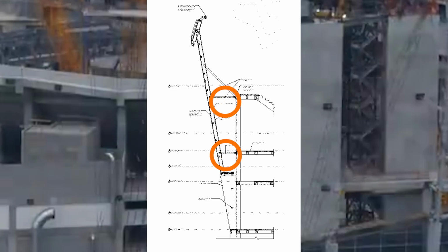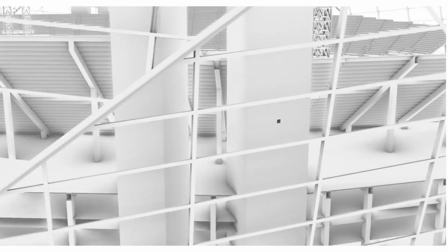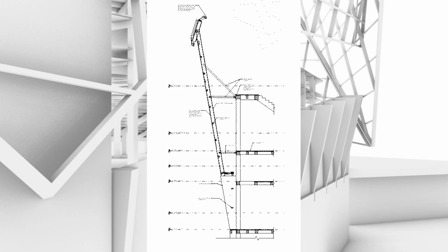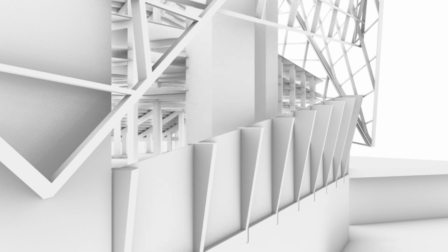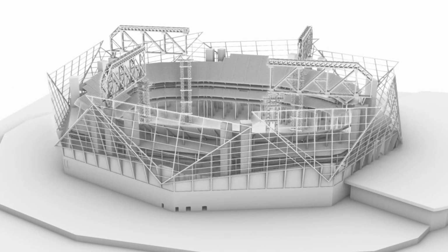The facade is connected to the main structure through two key systems. In areas with mega columns, steel arms from the facade frame are inserted into pre-embedded slots or anchor plates on the column, creating a rigid and load-transferring connection. In spans without mega columns, pin columns are used. These are slender vertical steel supports directly anchored to the foundation. Through this arrangement, they are designed to safely carry vertical loads from the facade to the ground.